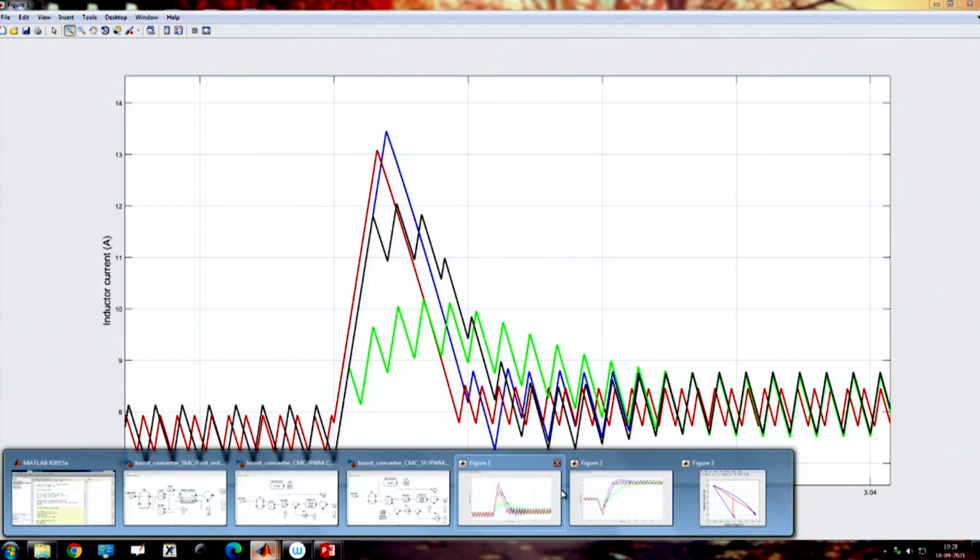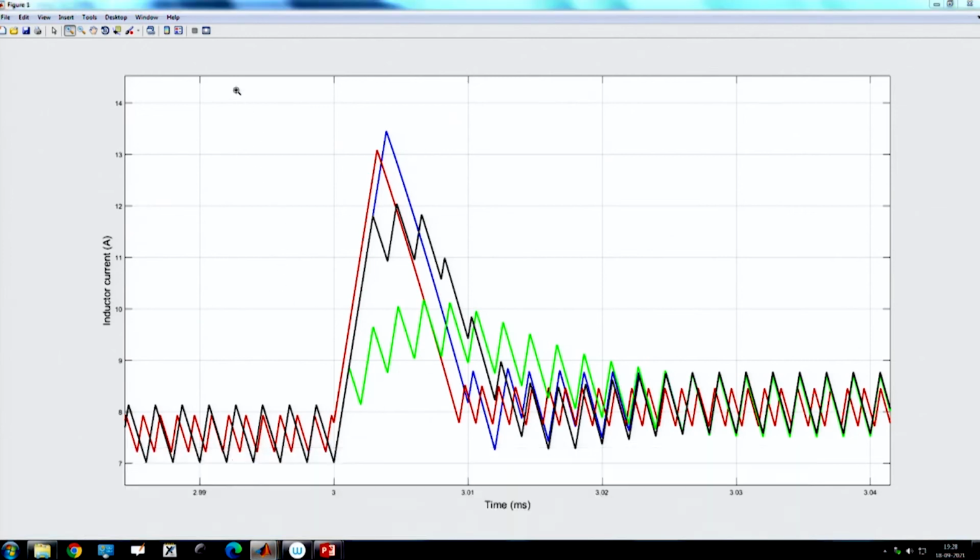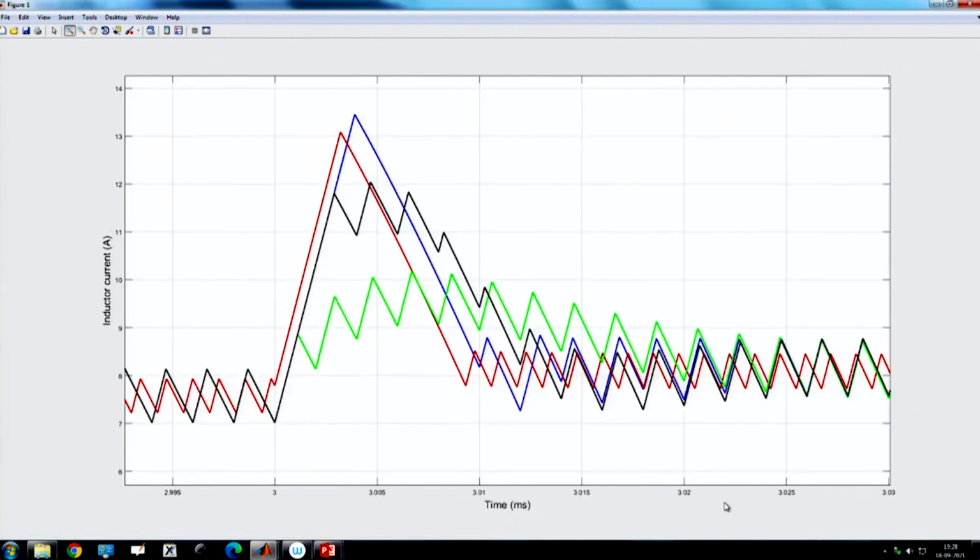But when you go for Lyapunov based stability and we have ensured the large signal stability is retained, then we can push to go beyond that. In this case the linear model and the bandwidth concept is not valid, but in some sense of bandwidth we can push the performance even much higher than what is possible using the linear model.